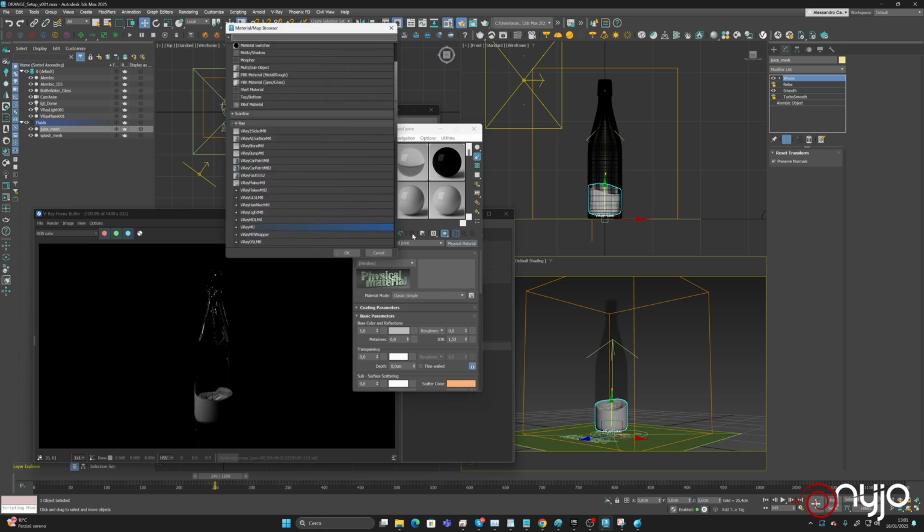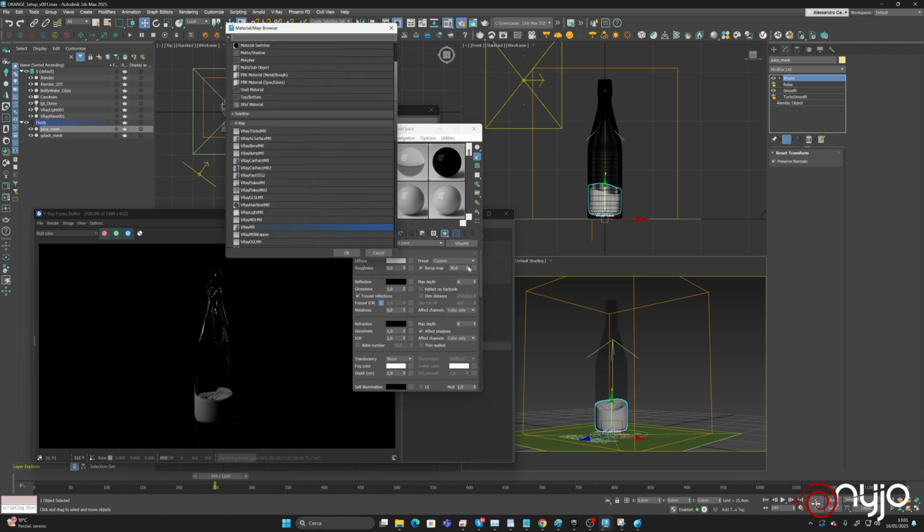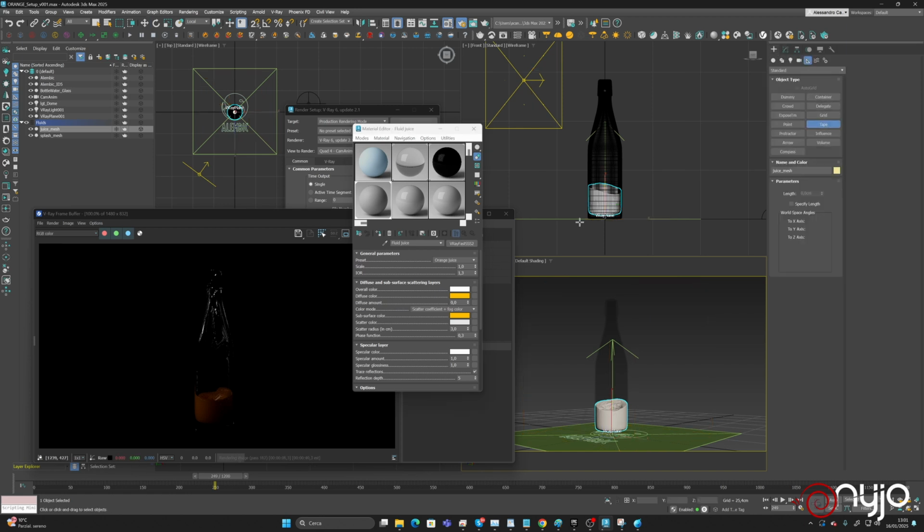And we start with a V-Ray material. We can try and see if we have something about it. No, so we can try to play essentially with a V-Ray fast SSS for the moment, and say that we go for the orange juice. We obviously have to take care about it. The first thing, we have to double check the scaling. So we are talking about 19 here, so 3 centimeters can be enough.